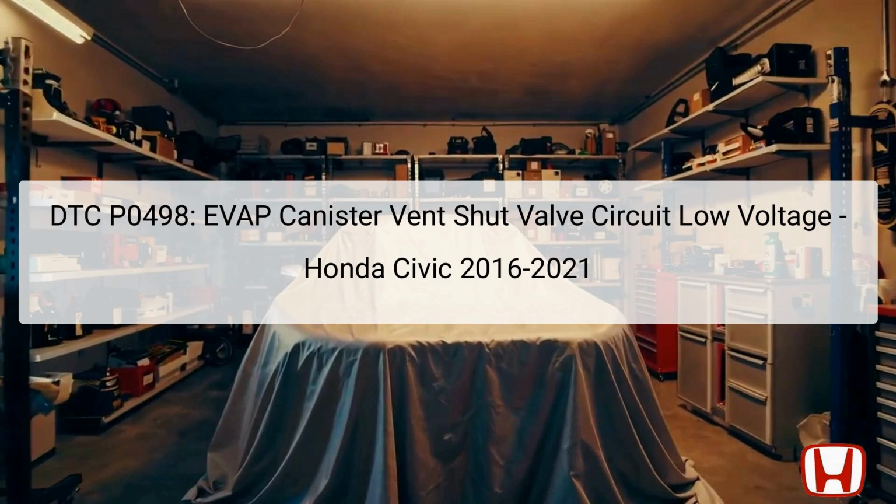The EVAP canister vent shut valve is located in the vehicle's evaporative emissions control system, typically mounted near the fuel tank or the canister itself. A malfunction in this valve can lead to excessive fuel vapors escaping into the atmosphere, triggering the check engine light and potentially impacting fuel efficiency.